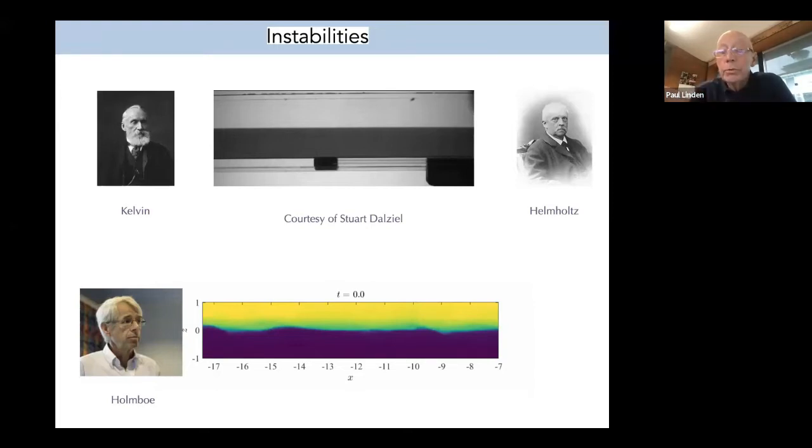So there's a density difference between these two layers. And in a moment, I'm going to start the video. You'll see the image tilt, and then we'll generate what's a classical Kelvin-Helmholtz instability. The lower picture is very similar. There are two layers of fluid, the blue dense layer and a yellowish light layer. And again, the flow is a shear flow. So there's flow to the right at the bottom and flow to the left at the top, which will be similar to what we see in the tilted tank. But you'll see the modes of instability look quite different. And I'm going to explore that and talk about that as we go forward. So I'm going to start the movies.